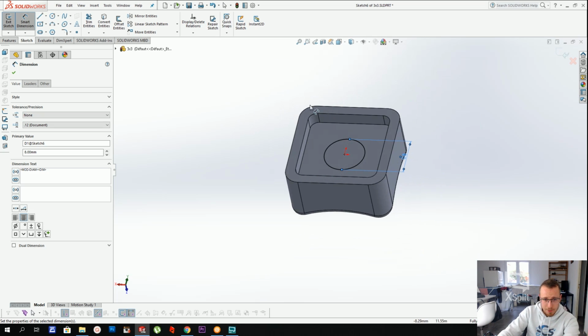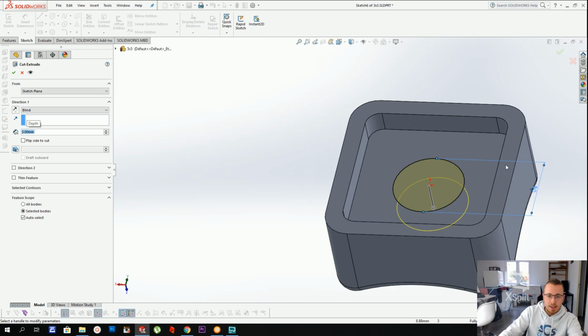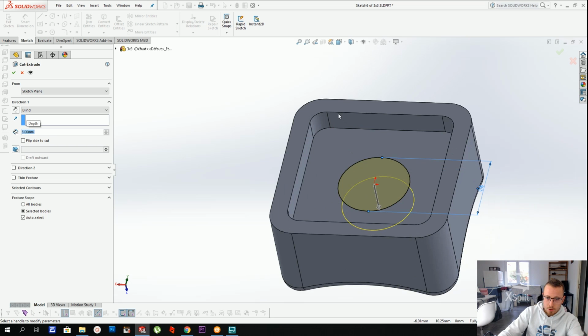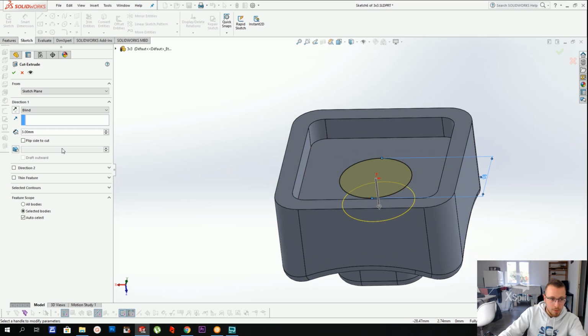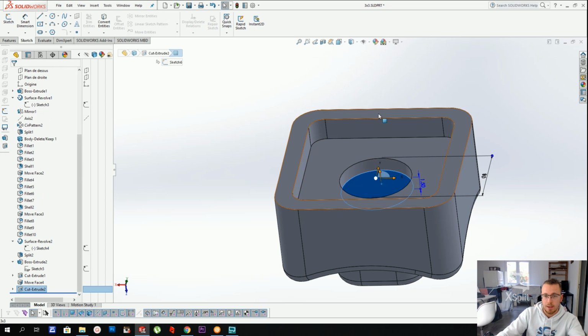So we're using a diameter of 8, and we're going to cut it down by about 3 millimeters. Now, technically, cutting this down, I created space for the screw. So technically, I would only need 3 minus the 2.5 that I've already cut out. But since we have a lot of margin, we might as well use, let's say 1 or 2, I guess 1.5 is fine. You just want the screw head to be in there and not touch the cap, that's all.